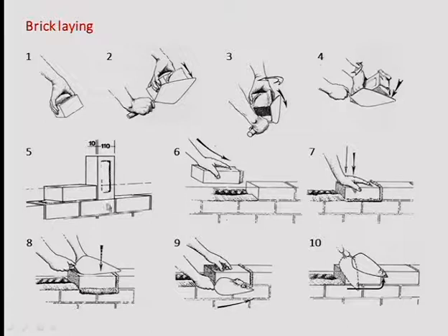So the first thing you do, you also place mortar here, number 6. You place the mortar also on the previous course of bricks. And you just put the brick in place, and then you adjust it. You just pick it slightly, okay? And then you adjust it, and you clean up the exceeding mortar. Then there is also another phase that you won't see here, but you can actually change the shape of the final joint, so you can clean it up even further.